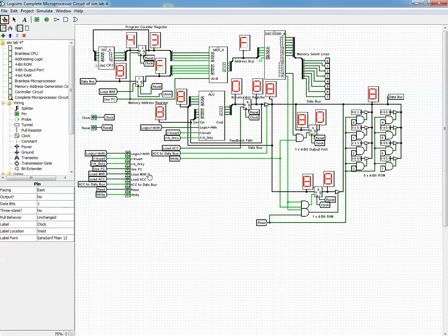And if you set ACC to data bus to 0, right now this data bus does not hold any data anymore. If you want to do any operation on this 8 at any particular time, as long as you do not press the reset, which is here, this 8 will be kept and stored whatever you want to do. So if you want to operate on this 8 again, this memory unit can be treated as a storage unit. It is in fact a storage unit, and you can move this 8 to this arithmetic logic unit.